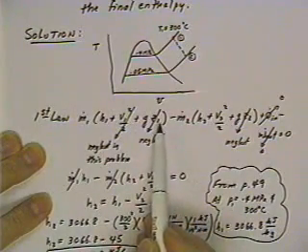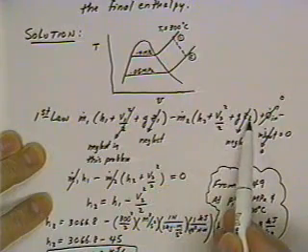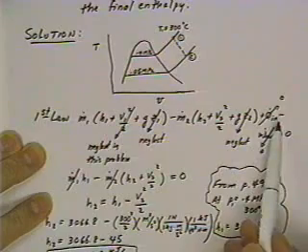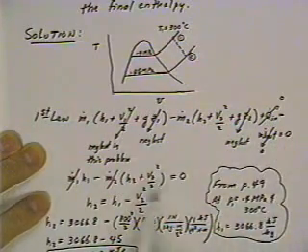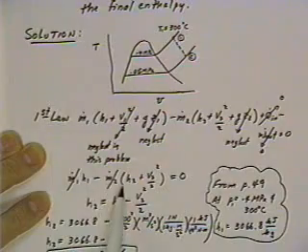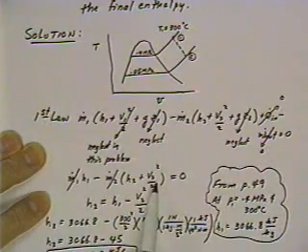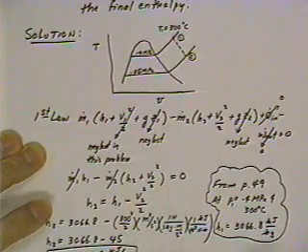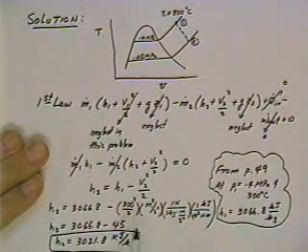We can neglect the potential energy term, and we are told that there's no heat transfer, and we know there's no work done. And so our problem really reduces down to enthalpy of 1 minus the enthalpy of 2 minus the kinetic energy, or the V2 squared over 2 term, equals 0. From that, we can then determine what the final enthalpy is.